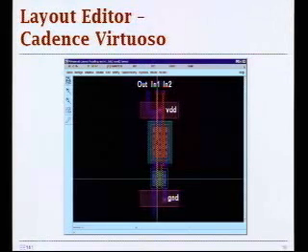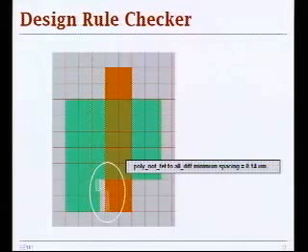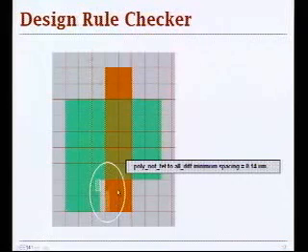Most of these tools have a so-called online DRC, so you can automatically check DRC on the fly as you do your layout, so that you can fix errors incrementally instead of waiting to complete a couple months worth of work and then fixing millions of errors. And this is the type of messages you get. This was MicroMagic. It will look a little bit different in your Cadence.